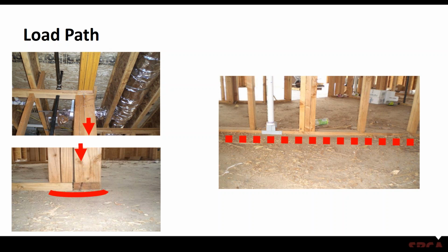And the floor framing members, and this is during construction, so there's really not a lot of load on this roof, but the floor framing members were not sized to carry any concentrated loads. And as a result, you're already getting a dip in the floor. And you see the same thing with the figure on the right-hand side. Again, there's a dip in the floor because of some fairly substantial loads that are coming down and just basically sitting on the floor.